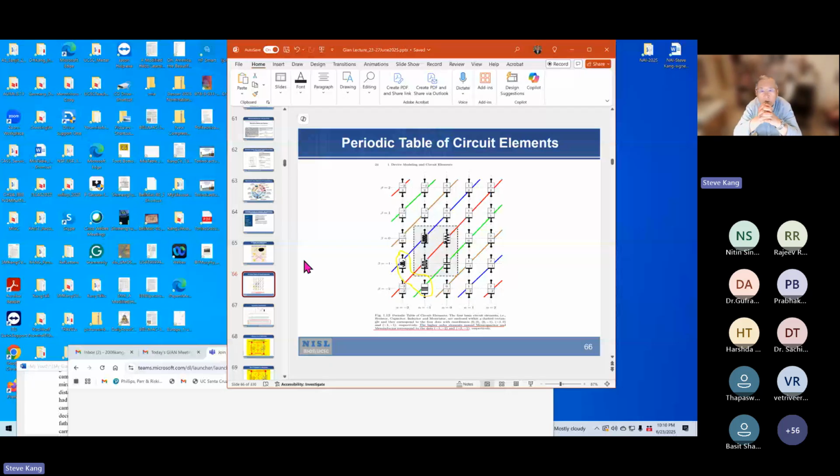That's huge. So you can have a programmable analog circuit using memristors, whereas if you have just a resistor, you cannot just go in and change the resistor. But with a memristor, once it is there, you can program it. So you can have a programmable voltage amplifier or different applications, or even neuromorphic computing. You can program different conductance values in a memristor array after learning and use it for inference. That's a huge application.